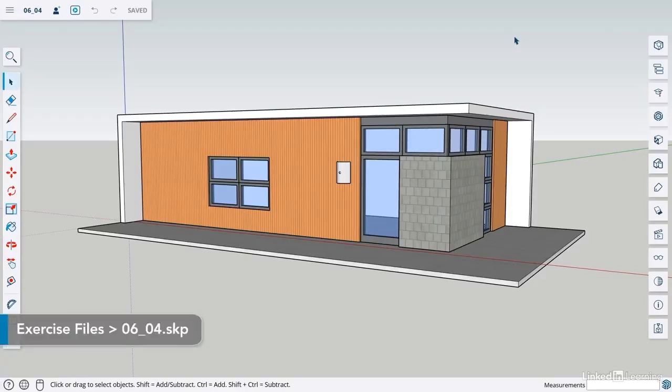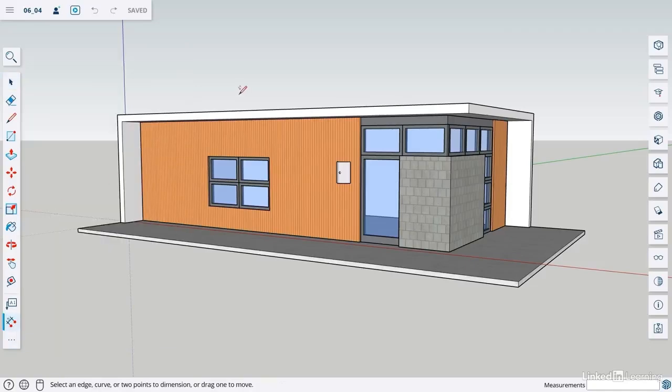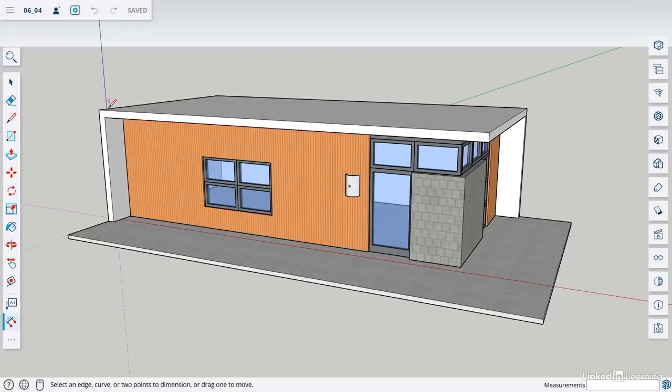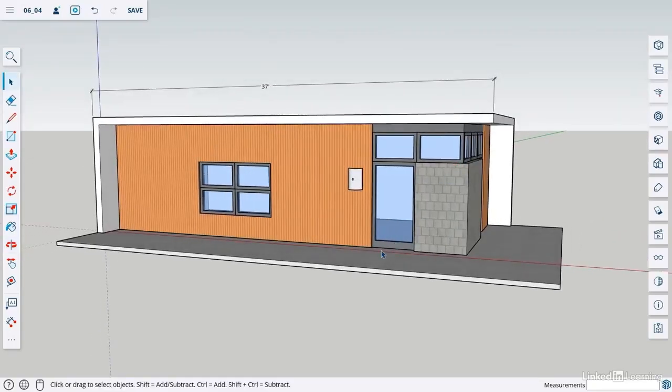And so this allows you to specify dimensions in your scene. So we can find this in our additional tools, dimensions. So when I select this, it brings up this tool, and all I have to do is left click, drag, and I'm snapping to these endpoints, and then I'm going to drag up because I want this dimension above that roof. So now I have that dimension.